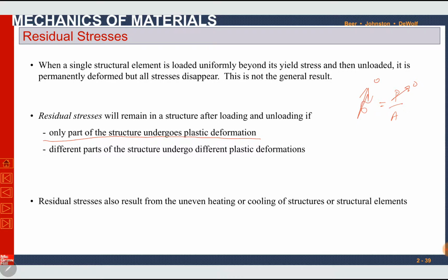Residual stresses also result from uneven heating and uneven cooling of structures or structural elements. So sudden cooling, sudden heating, or uneven heating and cooling also result in residual stresses in the materials and structures. So it is recommended to heat up or cool down materials gradually, not suddenly.